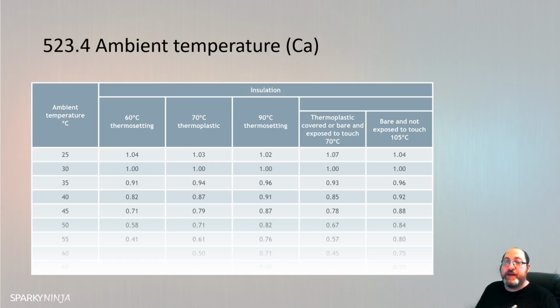So if I was to say that you're going to bury a cable and it's buried direct to 1 meter, you would then look at this. Buried direct or in buried ducts, it's buried direct 1 meter, 0.97. Okay, so this is all about buried cables and ambient air temperatures.